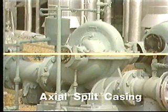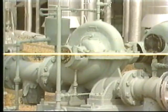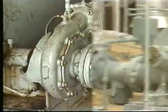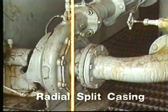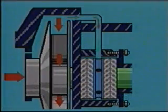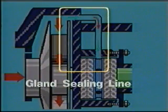If it is, the upper half of the casing can be removed, giving easy access to the pump shaft, impeller, and bearings. Radial splits are perpendicular to the center line of the shaft. The advantage of this design is that the casing can be made up in segments and bolted together to form one pump.